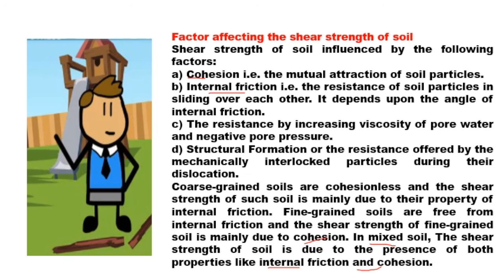In general, shear strength depends upon cohesion and angle of internal friction. For clay soil, it is cohesion. For sandy soils, it is the angle of internal friction. For mixed soils, it is a combination of both.